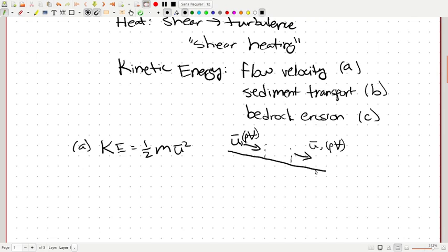The channel slope is the same, and so the channel velocity ends up being the same. And so as a result, we have the same velocity going in and going out. And so since energy is neither created nor destroyed, if we generate new energy in this reach right here by dropping the fluid from here to here, that potential energy becomes converted to other forms of energy, but it cannot be converted to kinetic energy to speed up the flow because the river is not accelerating.